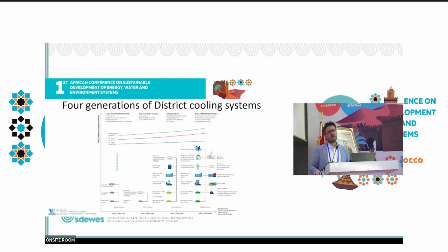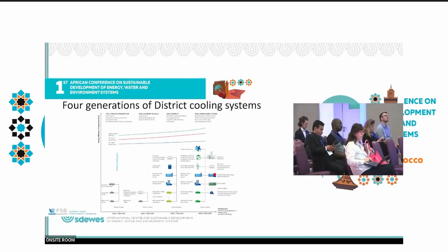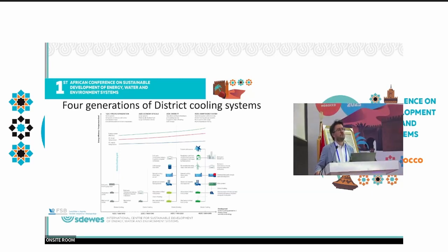And then we get to the fourth generation of district cooling, where we are now, 2000s, 2010s. And here, the main driver in the fourth generation district cooling systems is the overall need for decarbonization. This means that CHP, especially combustible fuel, is slowly starting to be left out. And I would say that the overall property of the fourth generation district cooling system would be the integration with electricity, but also integration with district heating. So this is one of the main components of these new systems. The focus is on exploiting both ends of the heat pumps simultaneously.